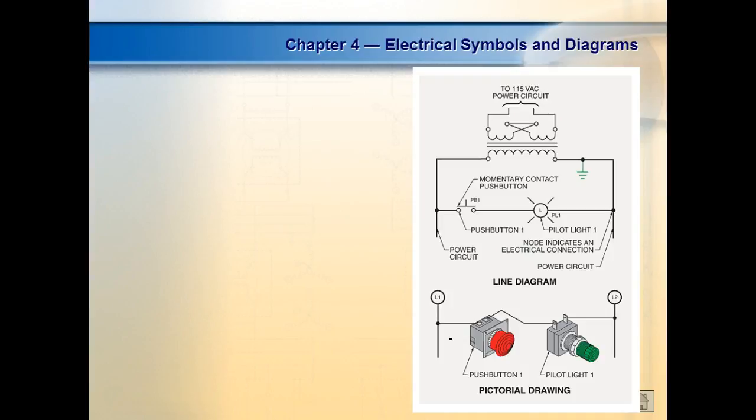But this is pretty much all the same. But ours, though, we're not grounded. We're not going to use grounded on the other side. When you go through a transformer, you're transferring that power magnetically, not electrically. So as soon as you go through a transformer, if the primary is grounded, the secondary is ungrounded. Y'all understand that? Ungrounded sometimes is a little safer in this situation because we don't have a lot of metal in this class. At home, ungrounded would not be good.